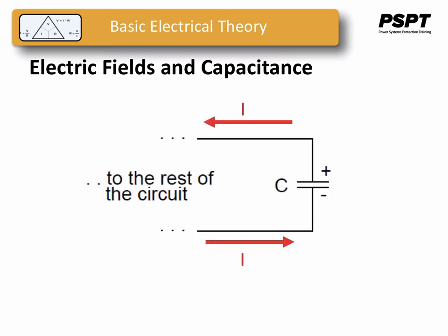Practically speaking, however, capacitors will eventually lose their stored voltage charges due to internal leakage paths for electrons to flow from one plate to the other. Depending on the specific type of capacitor, the time taken for stored voltage charge to dissipate can be a long time, even several years, with capacitors sitting on a shelf.